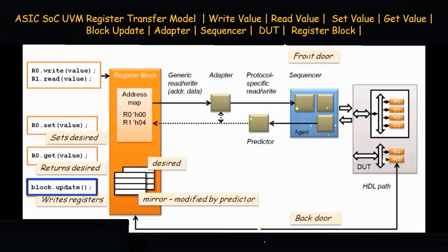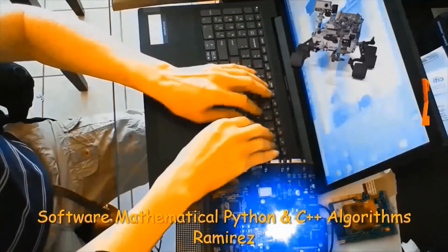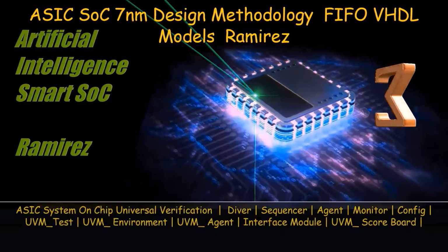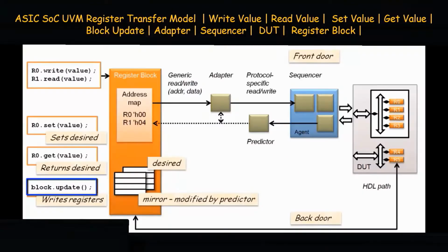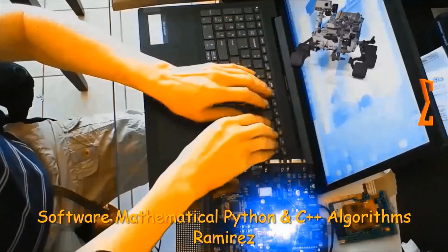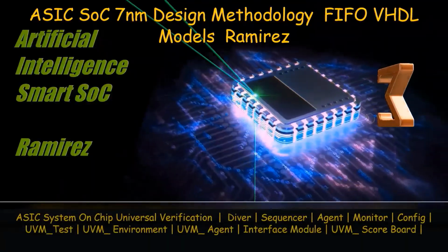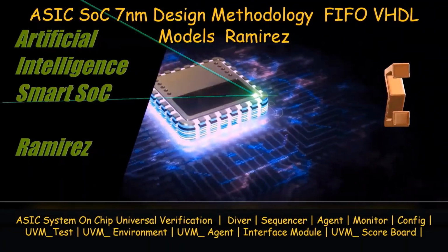Connected to the predictor, then to the adapter, and set the sequencer map, and then sets the auto predict to zero to expect explicit prediction. So the register sequence class, bus object, and utilities write and read to the register map, and then check the status value.